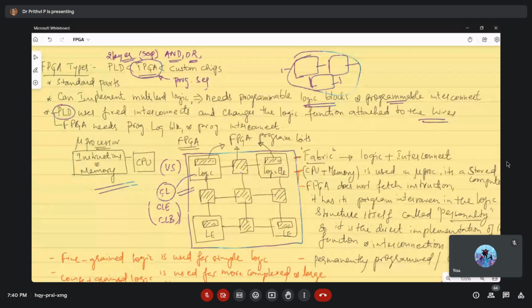Now there should be an interconnectivity between each logic block, so that there can be properly linked signals that are mutually dependent upon the iterative values, what is the outcome of one iteration, or multiple iterations if you can specify. So for testing, we need all the iterations to be evaluated. That means we need programmable logic blocks, and these are the logic elements. These are the programmable bits, or the interconnects which are connecting these combinational blocks.